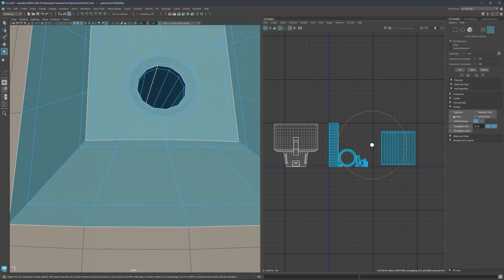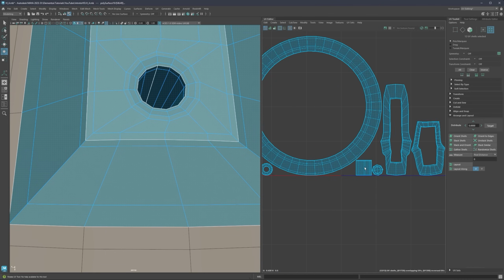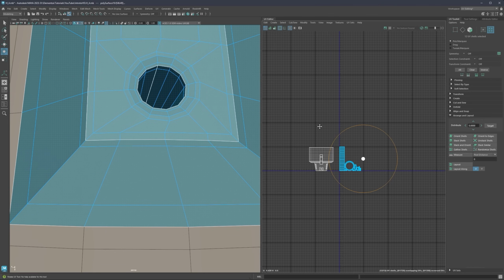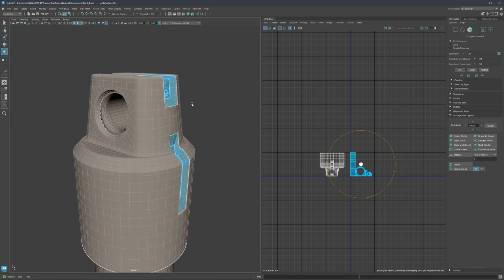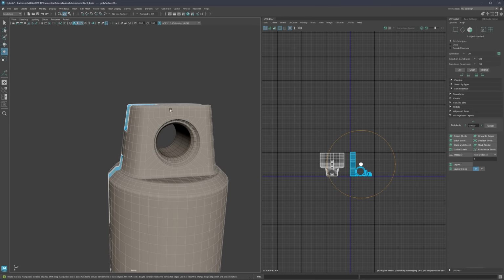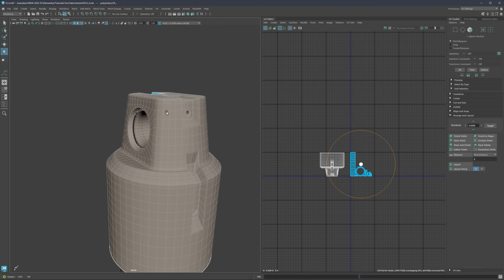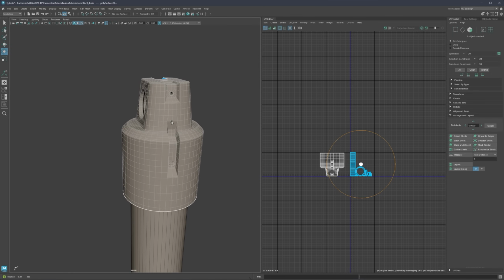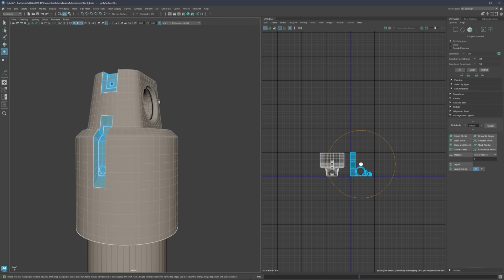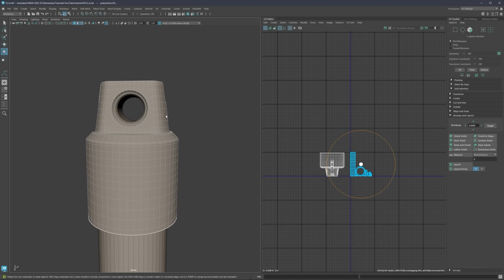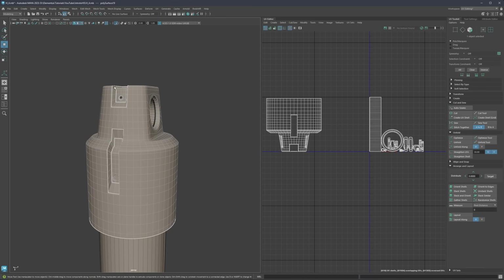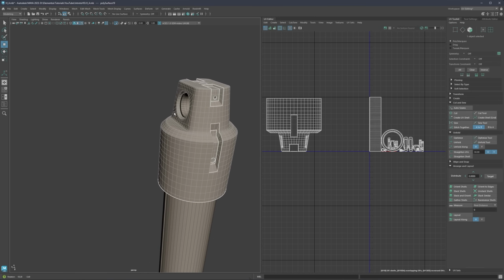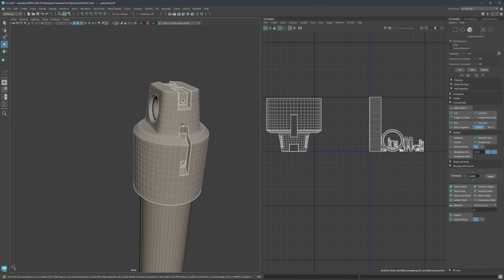So let's create a new cut, go to UV shell, move this now to the side, and now we see what we are getting. So now when we have more shells, you can always isolate and then you can see, for example, what results we are getting. So did I forget here something? Let me just undo here. Let me just see, yeah, okay, so here I forgot one. So we can push it here, select everything and just pack it together. And we have one more piece here left, which control one to isolate.